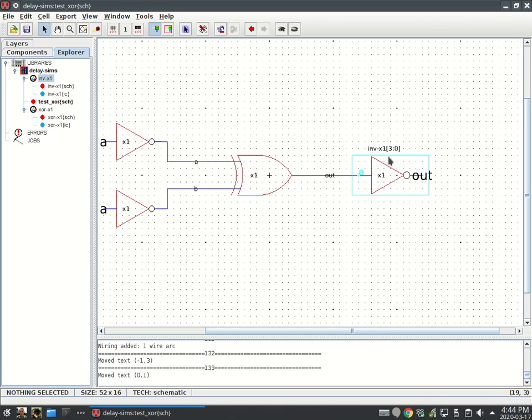If we do 1, 2, 3, 4, you're going to be maybe simulating what these fan outs look like, or what the delays are when the load increases. That's a good way to also see if logical effort, the technique, is legit. These inverters, because the input of the inverter is not affected by what's at the output, we're going to leave these nodes open and not worry about it. We just want to make a nice environment for our device under test.